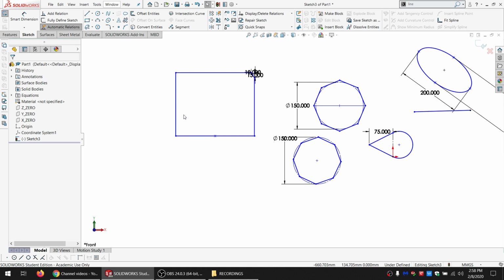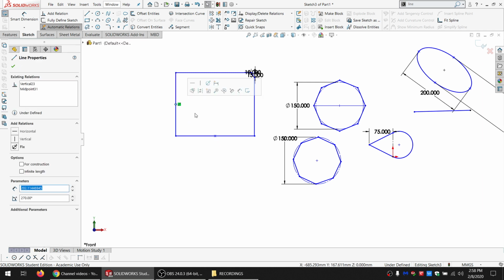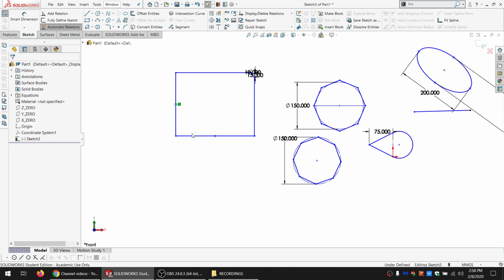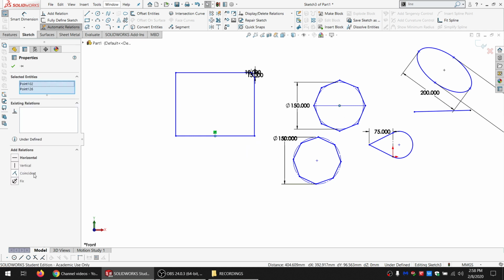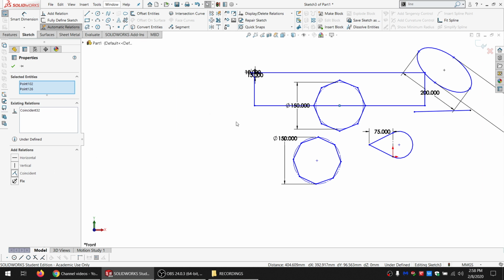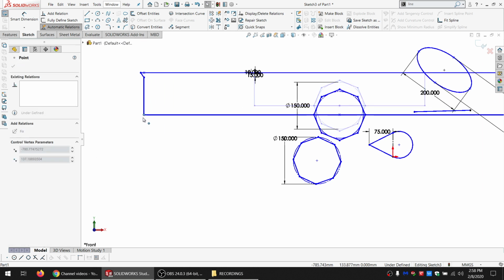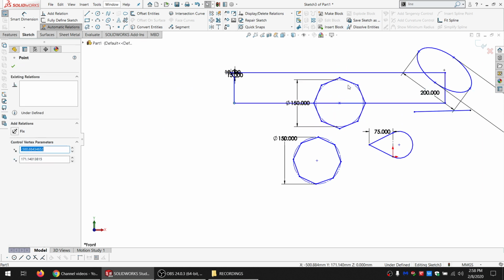All right, if I hover over this long enough, I can grab that center point, and that's the same as the point I made down here. The difference is that I can click that. That's the main difference. So now I can go coincident. And if the rectangle had been locked down, then this would have moved to it.